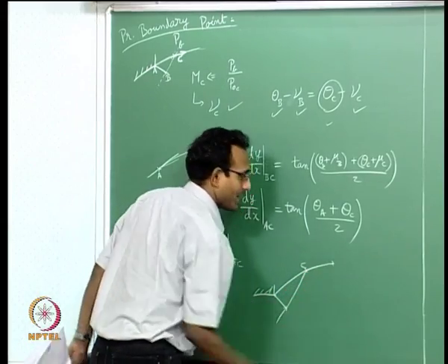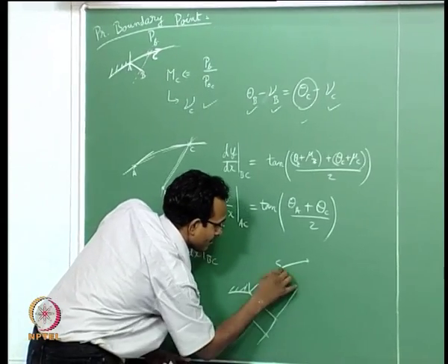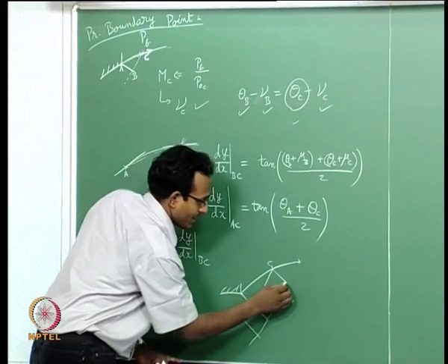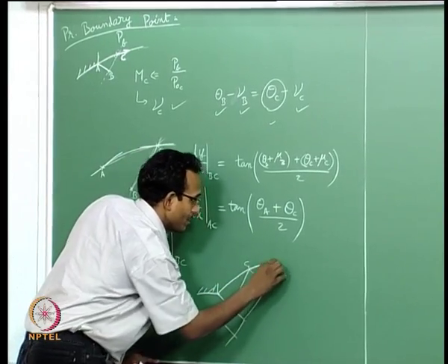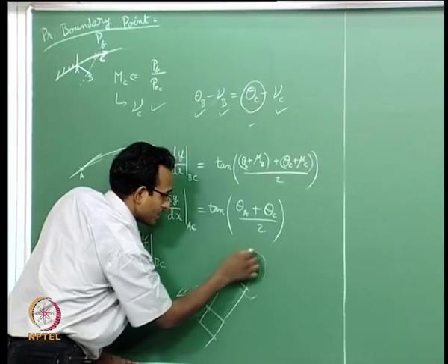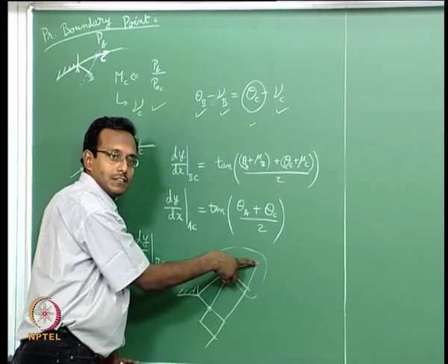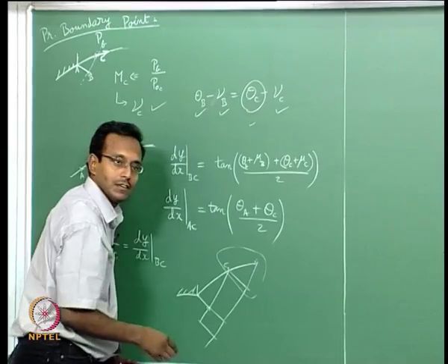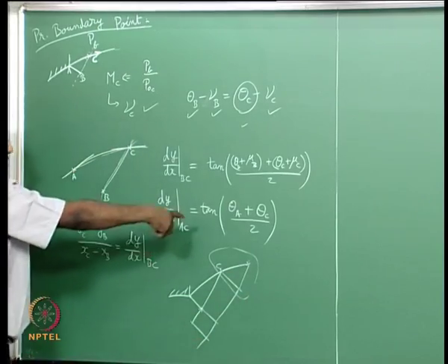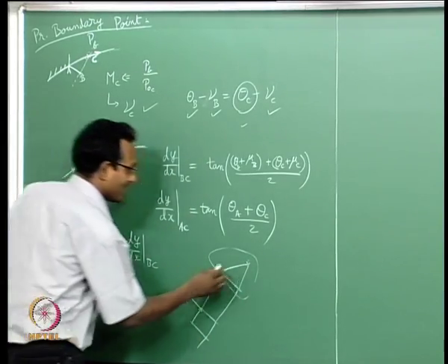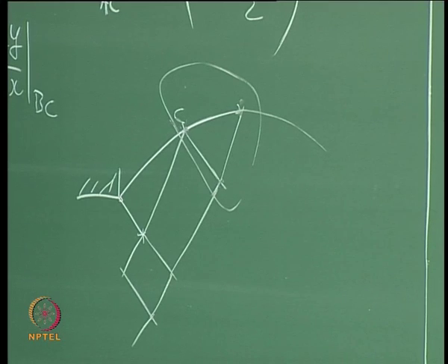Now, how will I find this point next? Of course, there is one more characteristic going from here, right. These 2 points will give you another interior point here. That interior point can now do exactly the same whatever we did with this analysis, these 3 points together. Now, this will become your new A, this will become your new B, this will become your new C. Okay, the new values A, B and C. Now, I will just take these 2 points as input, I will get this as the output, and that is the way I just keep continuing along this line. And you will notice that if the jet has to turn like this, the vector also turns naturally. The problem just solves by itself, you do not need to worry too much about it.